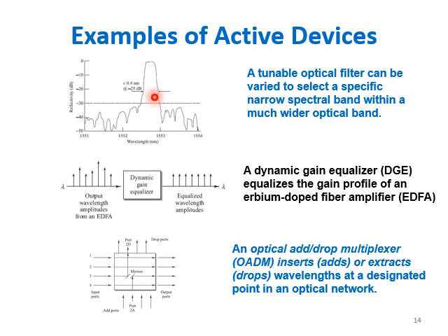That is normally required for WDM optical networks, where tunable optical filters are key. The diagram shows the reflection band and steep spectral profiles for a 50 gigahertz fiber Bragg grating, which is used to define the tunable optical filters.